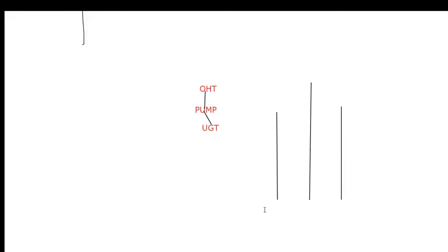See here, I'll mention it. So this one is our soil pipe. Basically we have three main drainage pipes. One is your soil pipe, another one is our waste pipe, then the highest one is our vent pipe. Majorly in each and every building there will be one soil pipe, one waste pipe, and one vent pipe.